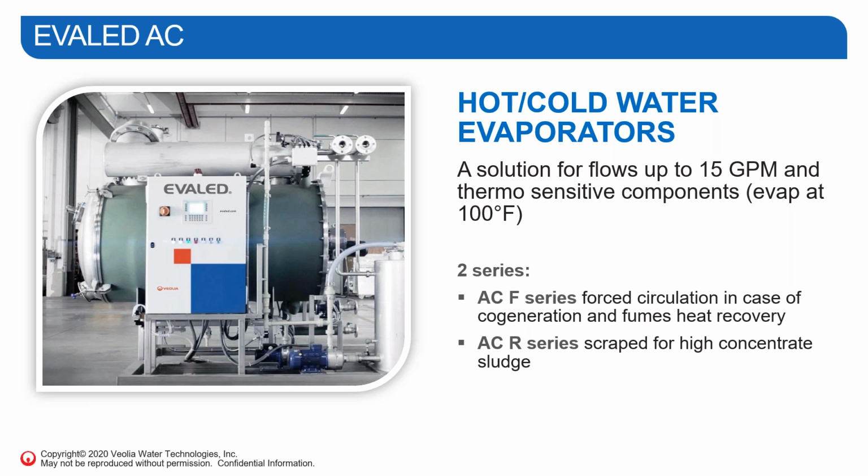The other big difference is it's no longer a completely enclosed unit with the freon gas. We're now going to use heat source from the industry. So if there's a cogeneration on site, you may have a waste heat source. This evaporator is going to take that waste heat source. We're going to run it through the heat exchangers, and that's how we're going to bring in the external heat for evaporation. So you can see that since we're using the vacuum and we're able to evaporate water at these low temperatures, taking that waste heat, which is currently essentially lost in the facility, is now going to be reused as a beneficial use inside of this evaporator. So that's one way that we can really keep our energy consumptions down.